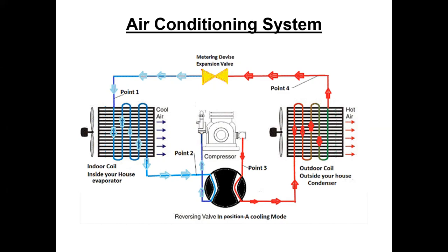So all that heat just leaps out. And so the air coming out of that condenser instead of 95 is 98, 99, 100. Who cares? It's still cool compared to 180-degree refrigerant. So that's how I dump it outside. And in order to make that cycle work, guess what? I got to put electricity in it. I got to turn that compressor. So that's how we do it.